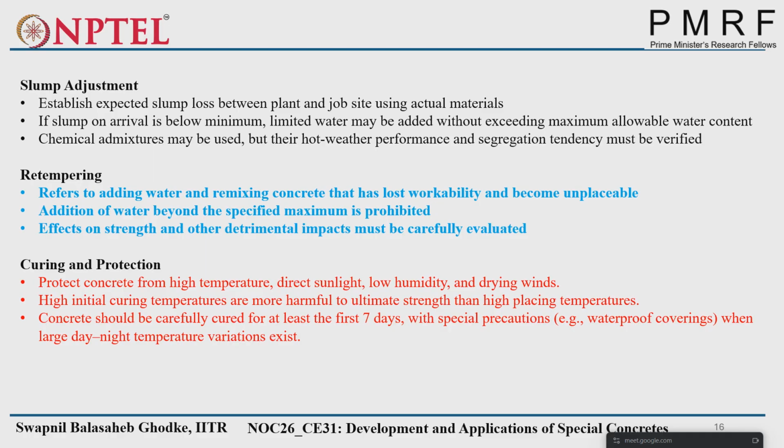The concrete temperature is already high and we are providing high water temperature, so it will enhance hydration. Early strength gain will occur because of the early hydration process.